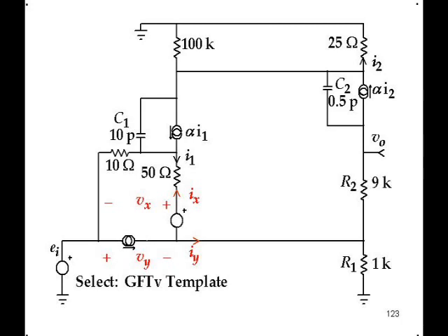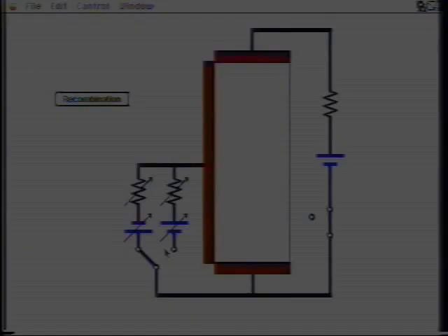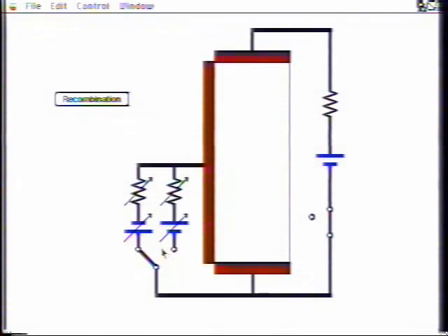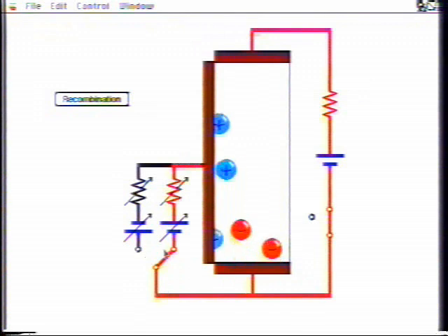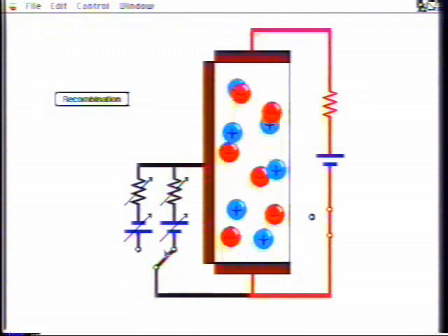Before we continue, I want to make a diversion to explain the device models that I've adopted in all the circuit diagrams. The intent is to show that both the BJT and the FET are charge-controlled devices, and therefore should be represented by the same equivalent circuit model. The basic operation of the BJT is exactly like the FET.